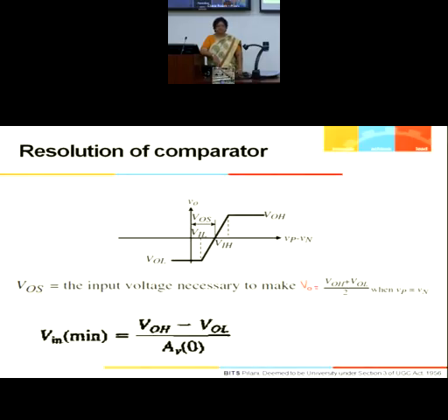So I will go for a certain design technique, auto zeroing, in my comparator. Because you cannot remove offset, you can only use a method of making it negligible. Some design technique you have to apply. So offset is going to play a very, very important role here, because it affects your resolution.